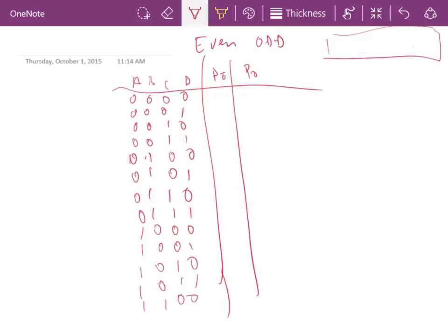And what we do is we set the parity bit to either even or odd, and you can do it either way. It doesn't make any difference. A lot of serial communications, if you're looking at serial communications from computer to computer, a lot of the early modems used serial communications, and you would use parity there. If you talk processor to processor, you would set up whether you would have even parity, odd parity, or no parity.